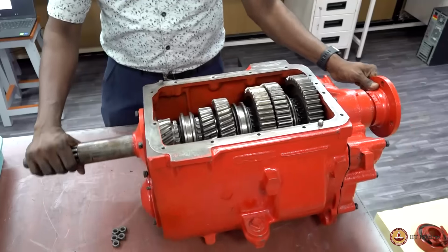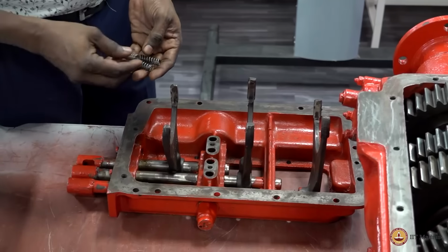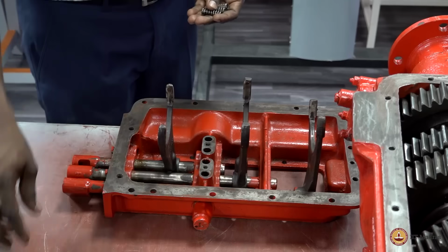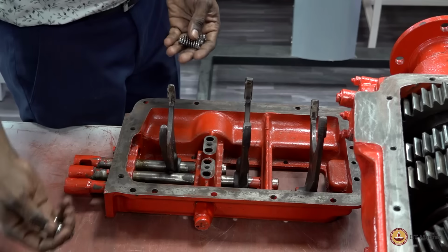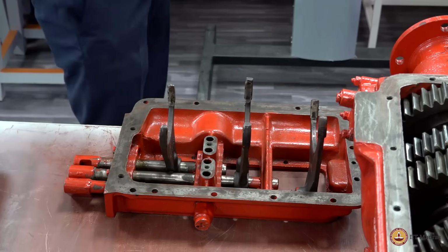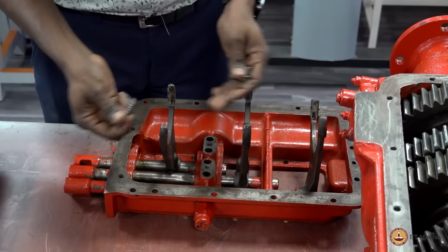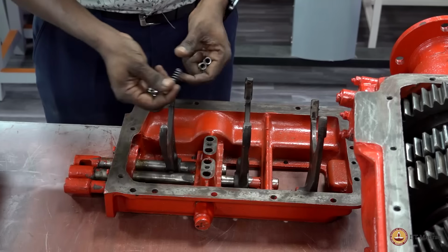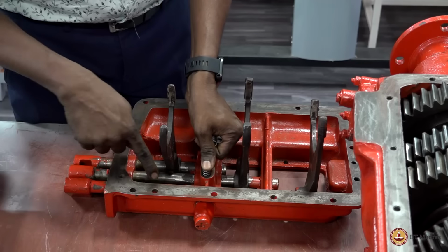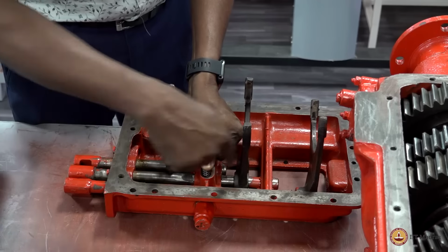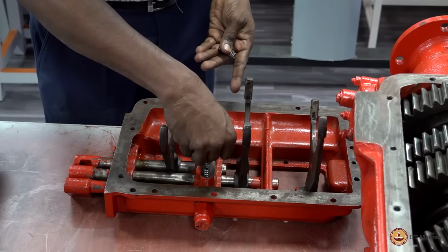Now I am going to cover the top portion of the gearbox. As we discussed earlier, there are 2 kinds of locking mechanism at the selector rods. One is the interlocking mechanism, the other one is the detent. This ball and spring arrangement makes sure the given selector rod will not come out from its engaged or neutral condition. For that we need to put a ball and a spring. This spring tension will take care of unnecessary movement of the particular gear selector rod. Likewise, for every single rod there will be 1 ball and a spring.